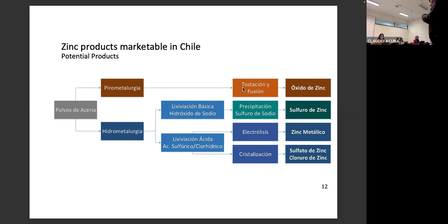XRD minerals is very important for us in order to understand what type of dissolution process, meaning leaching, we want to do, in order to know what the pH or redox potential conditions are, and then we come back to these Pourbaix diagrams. And then in between, we can do whatever we want as process engineers. But before going to the process design or the decision, which we call the route path or the process path, we need to seek what type of product we can have.